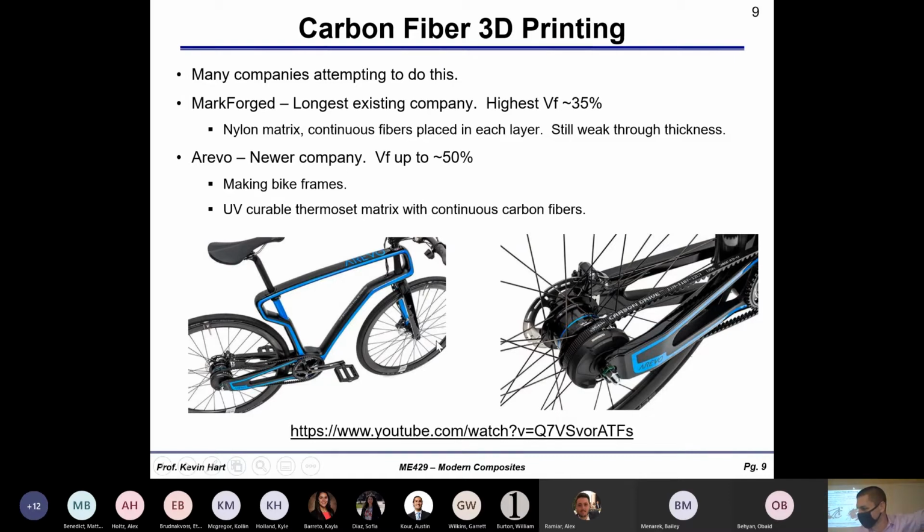The idea here with this bike frame is that they're printing it with this frame element on the bed of the 3D printer, and they're building it up, which would be sort of like the width direction of this bike frame. All right. And what they're doing is they lay down fiber and they lay down a UV resin that's combined with the fiber, and they immediately follow that fiber roll that they're laying down with a UV light.